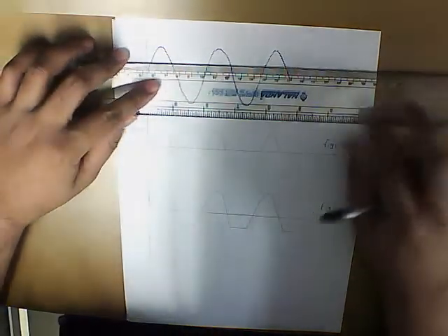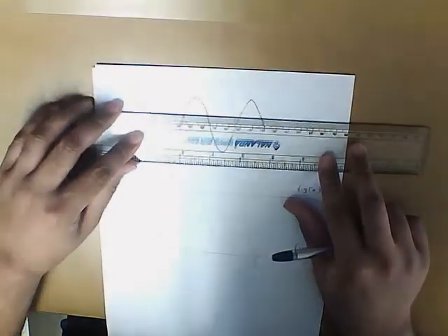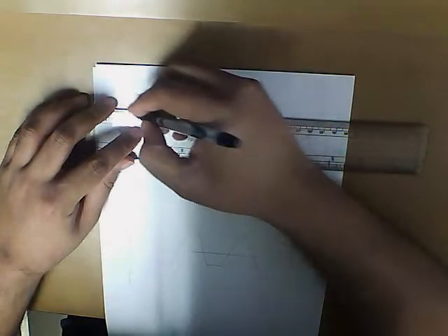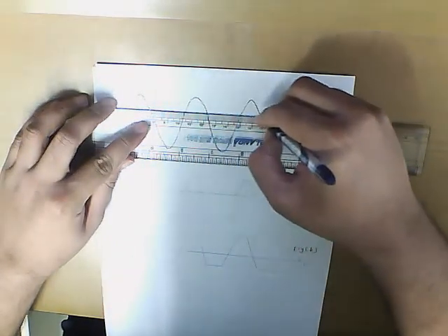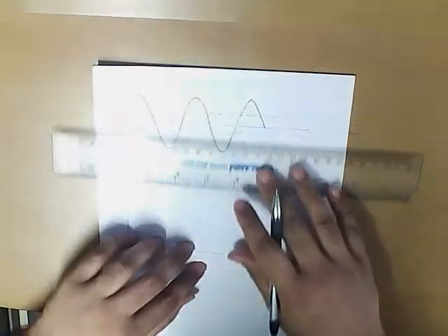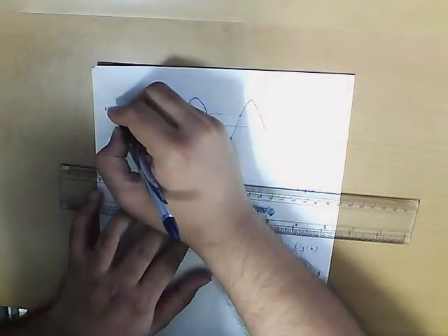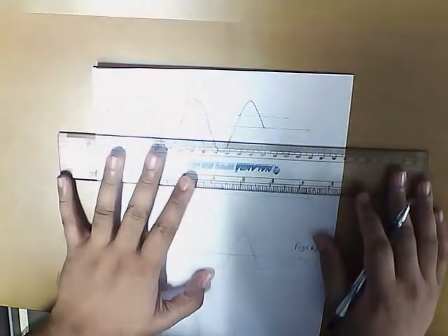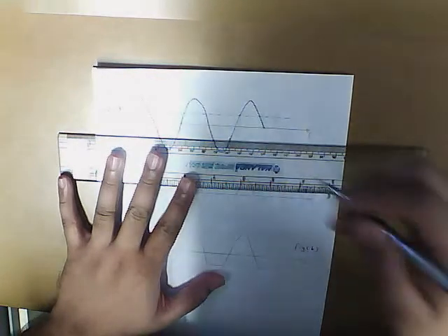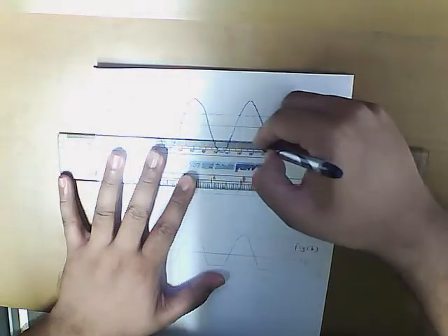In figure A, my voltage is V plus 0.7. I show V plus 0.7 here. So I name this level as plus V plus 0.7, and just below that, minus V plus 0.7 is going to be a negative voltage level, because minus V is much greater than 0.7.